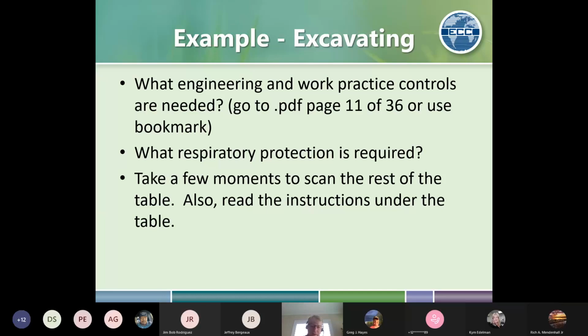So that's basically a high efficiency filter. It's not exactly the definition we would use in industrial hygiene, but it's very close. And of course, it has to have heating and cooling capabilities, and I would add, that work, because if they don't work, you know what the operators will do. So it has to meet all those criteria to be considered an enclosed cab.